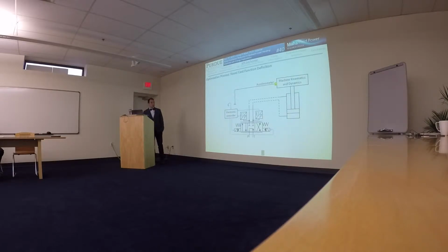So my effort was to try to find a new formulation in order to make this approach general. And of course, we have to avoid the use of the accelerometer. So now what I did, I use what's left, which is the pressure signal. In order to minimize the oscillation, I used the high-pass filtered signal, which gives the oscillation content of the operation.